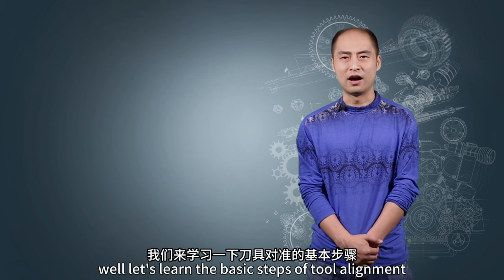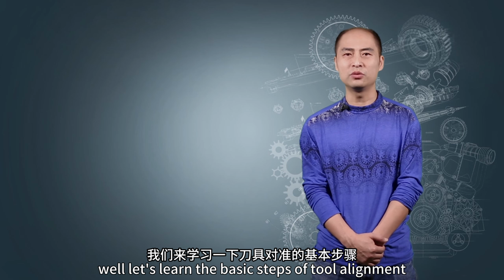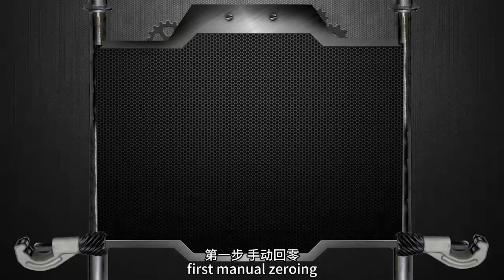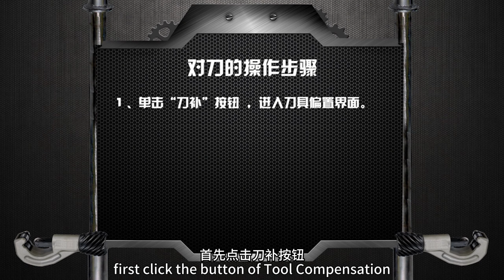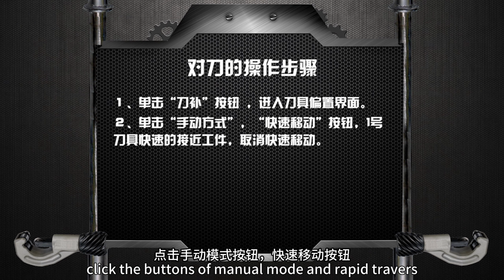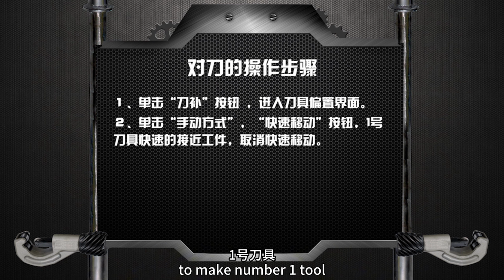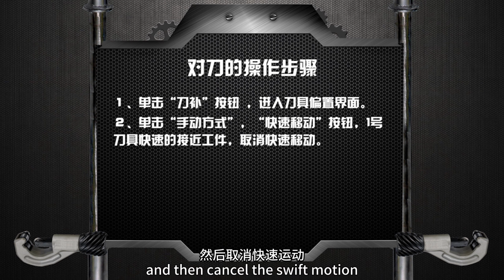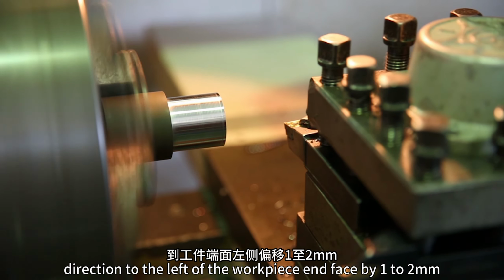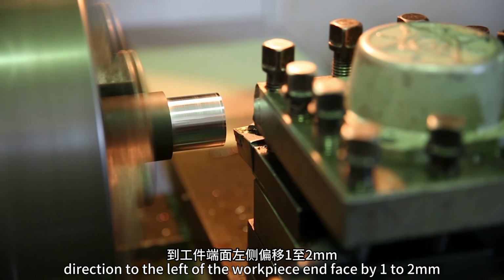Well, let's learn the basic steps of tool alignment with the example of the 93 degree cylindrical turning tool. First, manual zeroing. First, click the button of tool compensation to enter the tool setting. Second, click the buttons of manual mode and rapid traverse to make number 1 tool get closer to the workpiece quickly, and then cancel the rapid motion. Third, move the tool in the negative z-axis direction to the left of the workpiece end face by 1 to 2 millimeters.